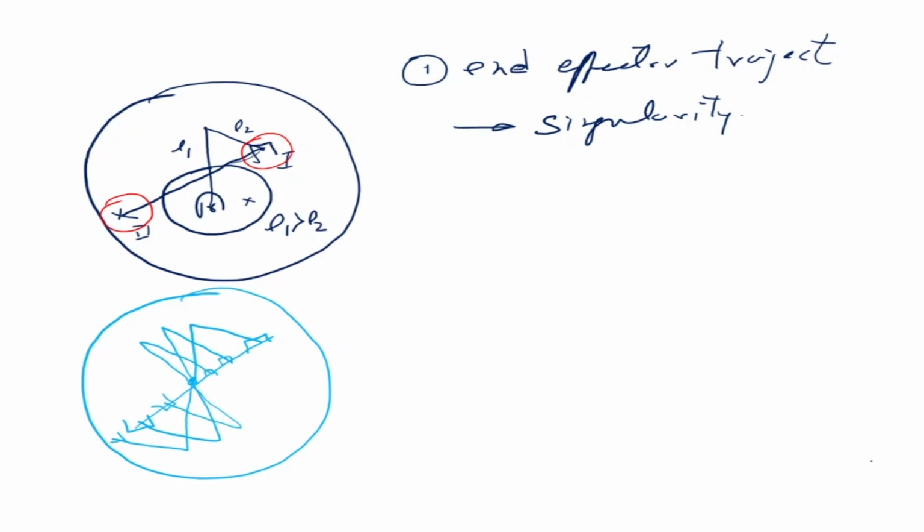What you're seeing is that in this position orientation, the manipulator is facing that side. In this position orientation, the manipulator is facing this side now. So these are inversions of each other, right? So this also is a problem, that suddenly there is an inversion which is taking place somewhere in the center, and this is not preferred.